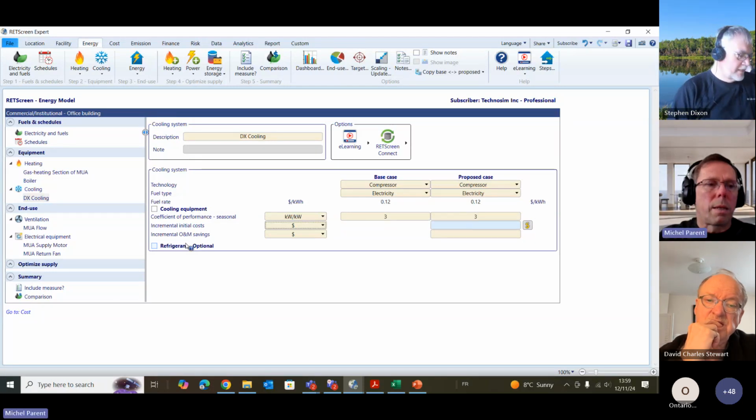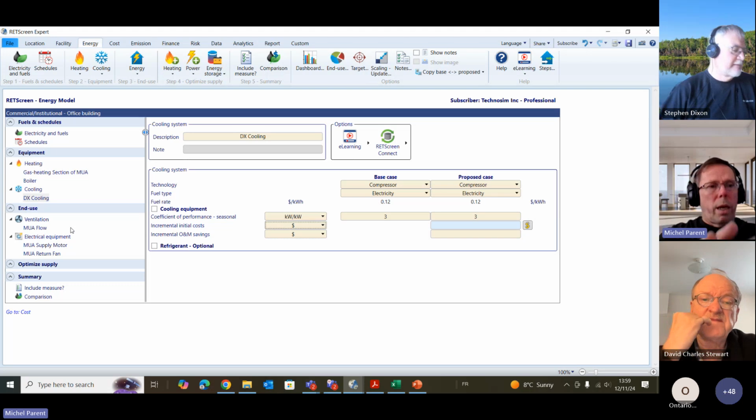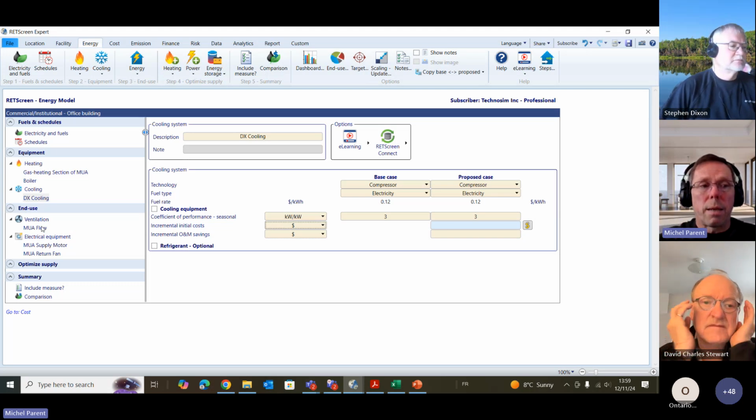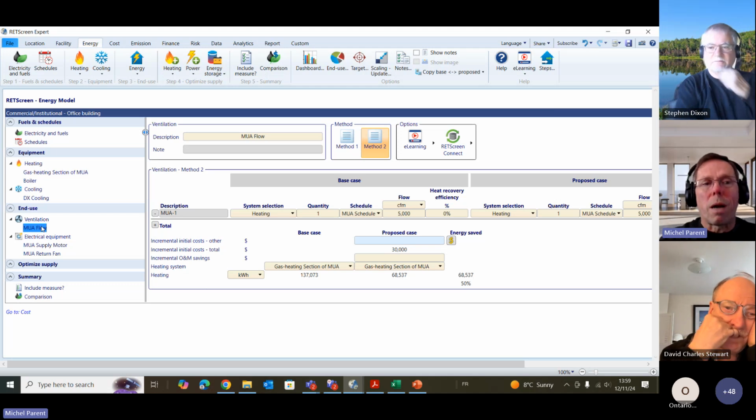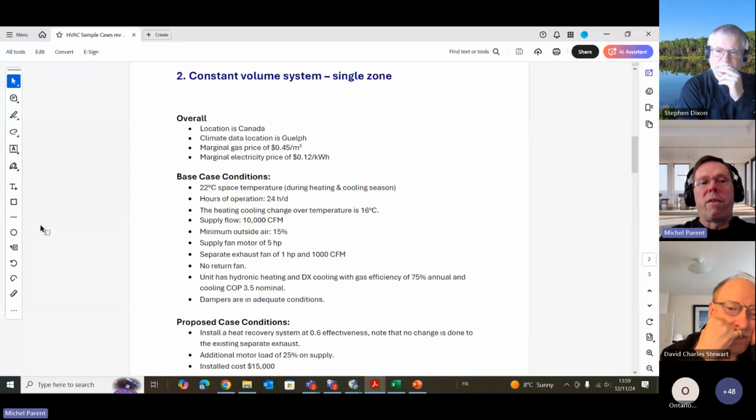Yeah. All right. So we're done with our heating and cooling. We're going to go back, and now we're going to change that ventilation system that is preventing us from deleting those components we don't need anymore. Obviously, if you start from scratch, you won't have that issue. It's not really an issue. So we're going to go and define the ventilation component of that rooftop unit.